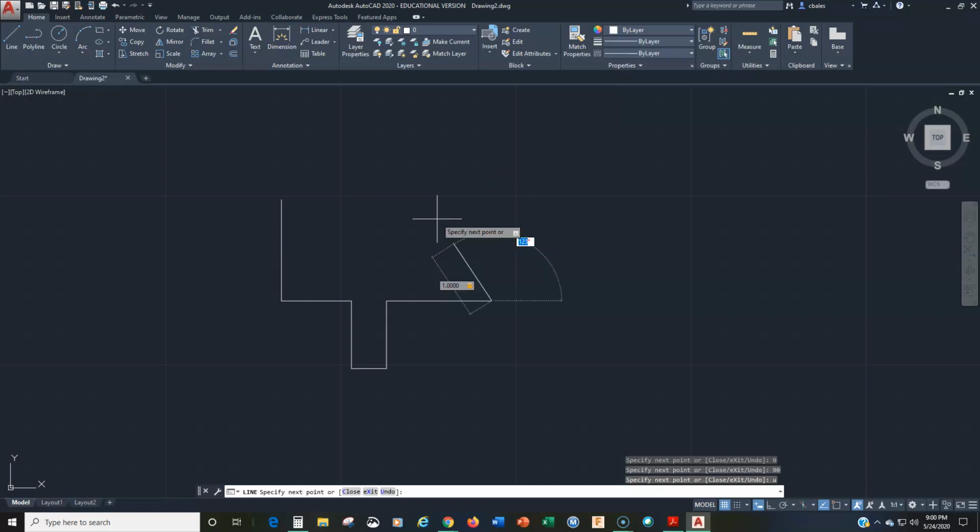So how am I going to do this? 1, tab, I want to go down either all the way around to 270 degrees, or I want to do minus 90. So I'll do both and show you. Look, 270 means starting due east, I'm going 90, 180, 270 degrees in a counterclockwise fashion. There we go. Or let me undo that, and let's go 1, tab, and let's do minus 90.